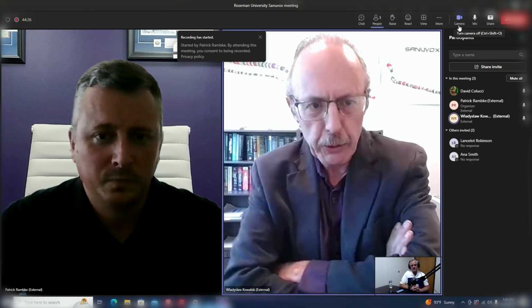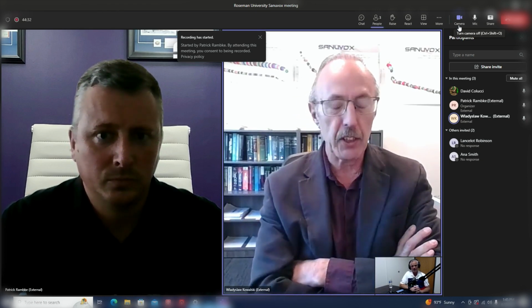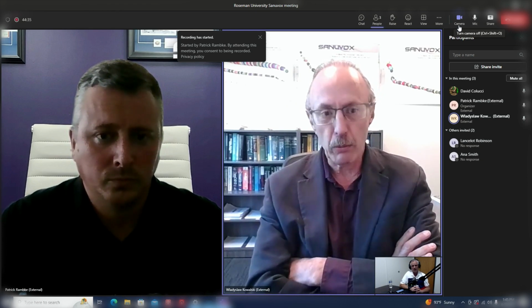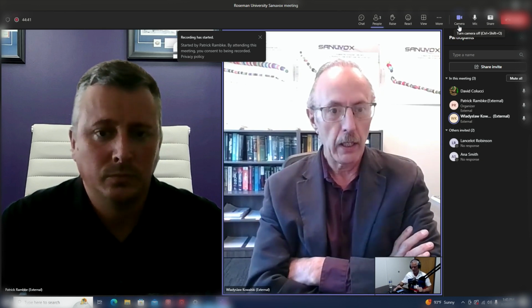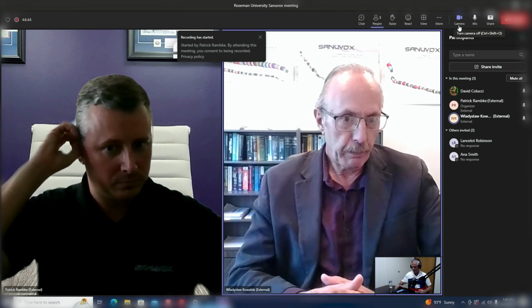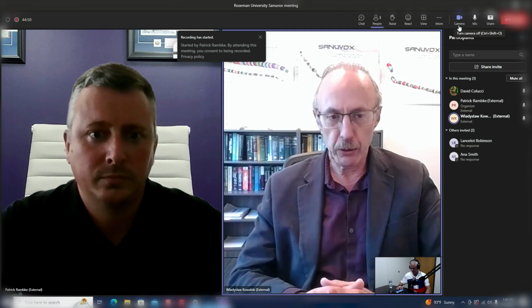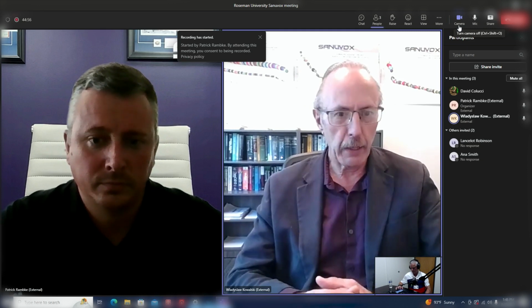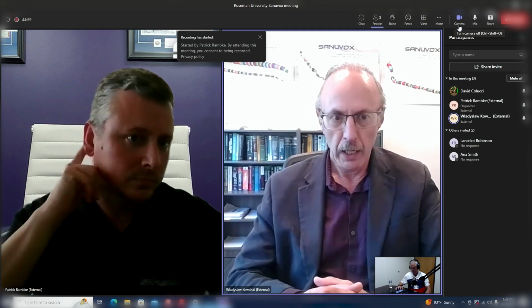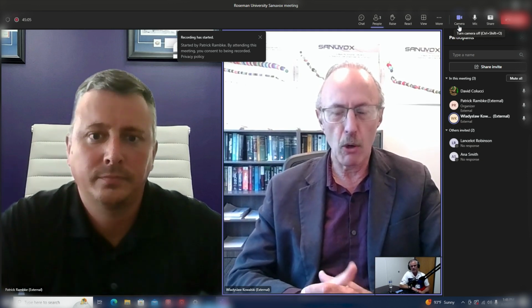Sure. I'm in ASHRAE. I'm on the ASHRAE Service Disinfection Standard Committee. They also have a standard for testing UV systems. They have a model room standard in which any kind of air disinfection system can be tested and certified for its performance. ASHRAE's been fully supportive of testing standards for UV. And it's clear from ASHRAE 241 that they accept UV, in the sense that if it can produce an equivalent air change rate, it can be used in place of outside air. It is implicit in the ASHRAE standard, and it opens the door to a wide variety of applications.